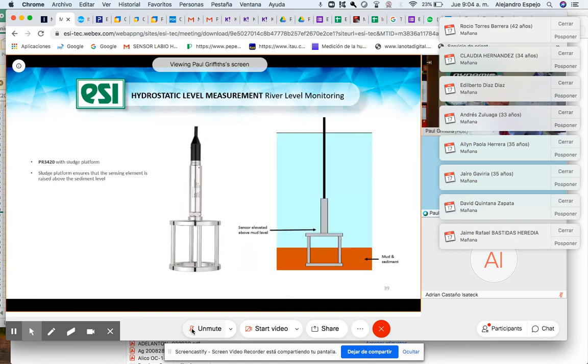This is an example of a river or lake, if you like, where you have sediment on the bottom. It could be anywhere really, but quite often when the transmitter is lowered to the bottom of, let's say, the river in this case, the nose cone may go into the sludge or the mud at the bottom. And if the sensor becomes blocked, it will stop reading.